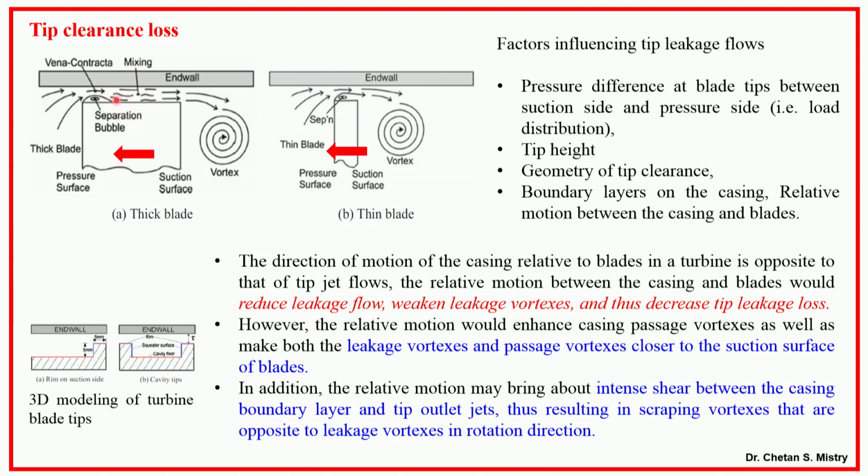So this is the particular region where I have growth of the boundary layer, one flow is crossing, and the whole mixing is occurring, and that generates one vortex. That vortex will try to move downside. Now my incoming flow is coming from one side, I have my tip leakage vortex, and they combine together and try to move more towards my suction surface. So this is my tendency.